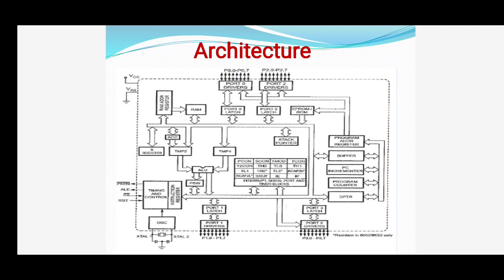Drivers are required to drive the port when working as an output port. Then we have RAM and the RAM address register. This register provides the address to the RAM for reading and writing operations. That is, the RAM address register enables one of the locations of the RAM.